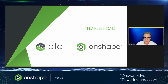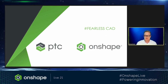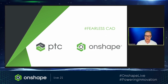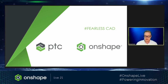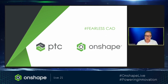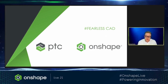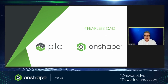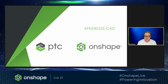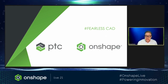So our company works with other companies and divisions that use a variety of CAD products. We need to be able to integrate their data into our design work. Is this possible with Onshape? Absolutely, yes. So Onshape supports standard 3D formats, such as, of course, the native Parasolid format, but also STEP and IGES, as well as other native formats, such as Creo, SolidWorks, Inventor, CATIA, and NX.